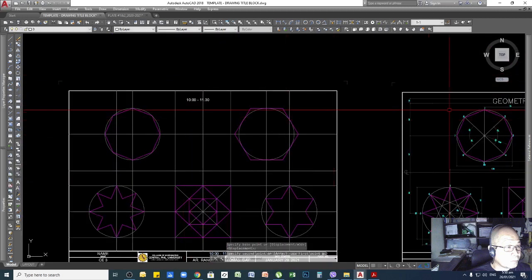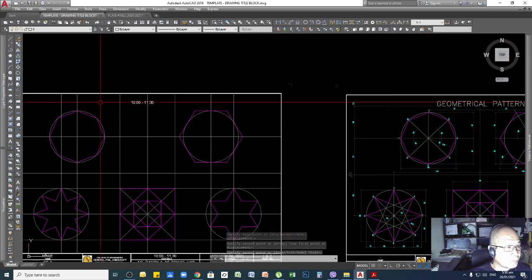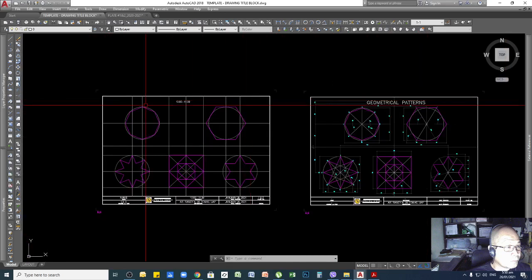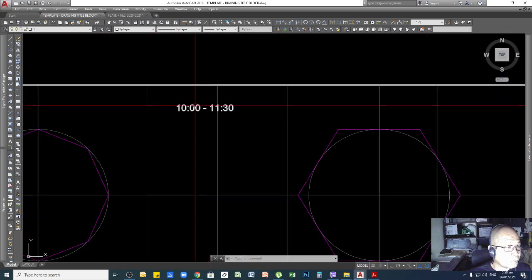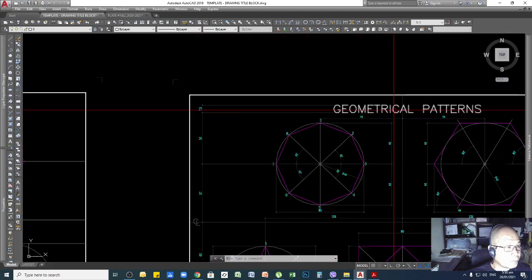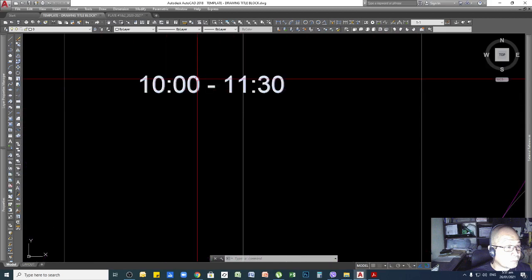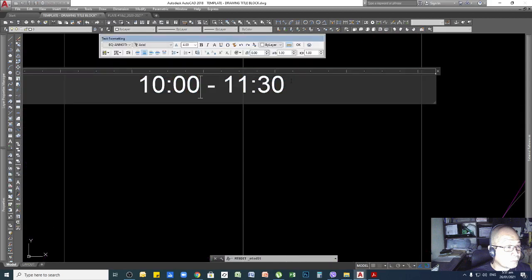If you need to follow this one specifically, you can do that, but as long as you have the title here, it doesn't matter. That's good, that's okay. So this is much bigger than this one. So all you need to do is change the size of this by double clicking, so it will come out. You can see here that this is the height of your text. You can change this to, let's say, 7.5.